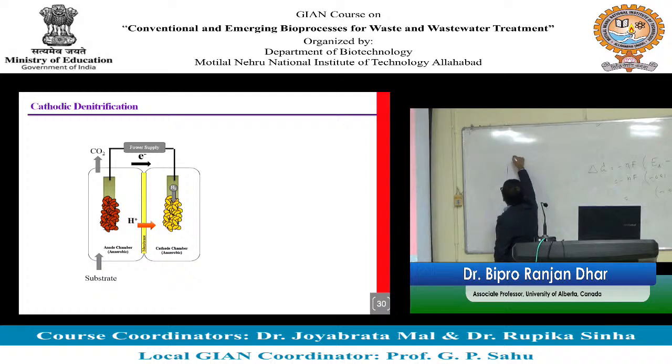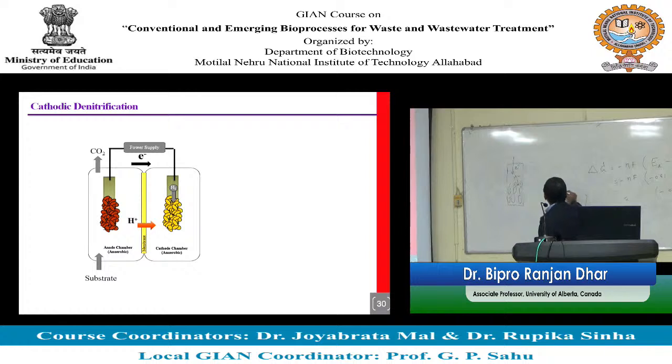So from the reaction, electron is coming to the cathode, right? And you have protons, and you are converting that to hydrogen gas, which is an electron donor. And when you are feeding, let's say you have an aeration tank, you provide oxygen, you have already converted all ammonium to nitrate. So if you pass this, let's say you have a cathode chamber, you are recirculating between two tanks. So you are basically feeding nitrate there.